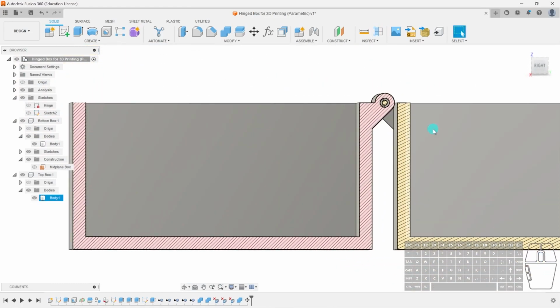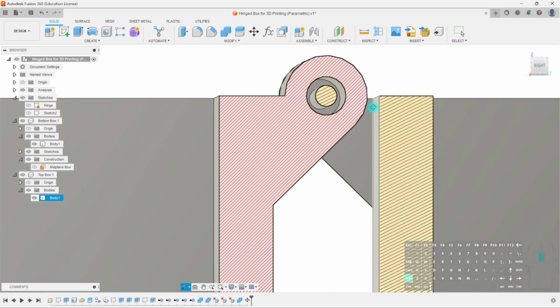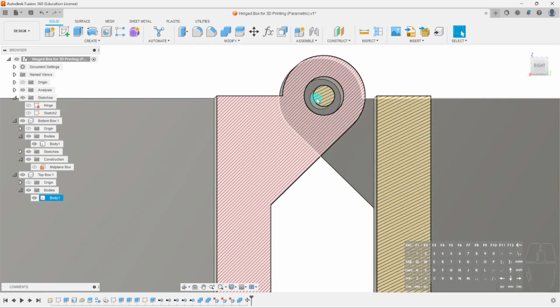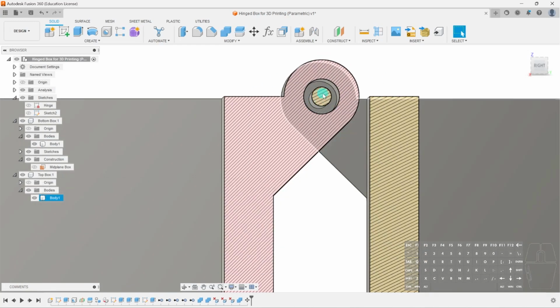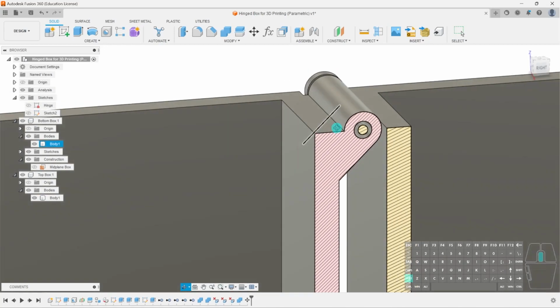Okay, you can see that actually what will happen is it will print a straight line, but we have it encased and it's thick enough that as it's printing the lines, you don't actually need to support it. It won't be the best. Obviously, this will play with isotropy and whatnot. But if you try it out yourself, you should be able to print this and have it print in place without the use of supports.